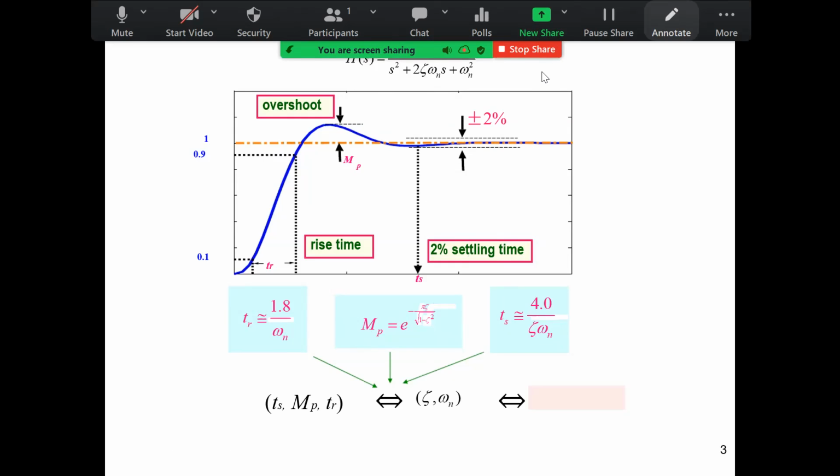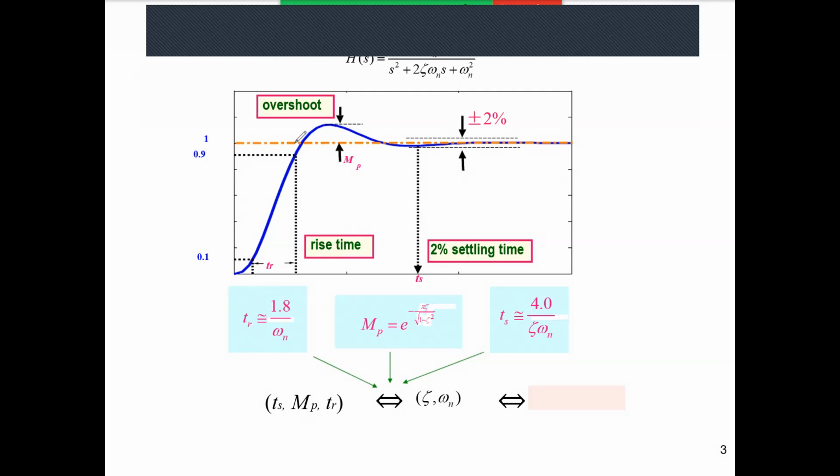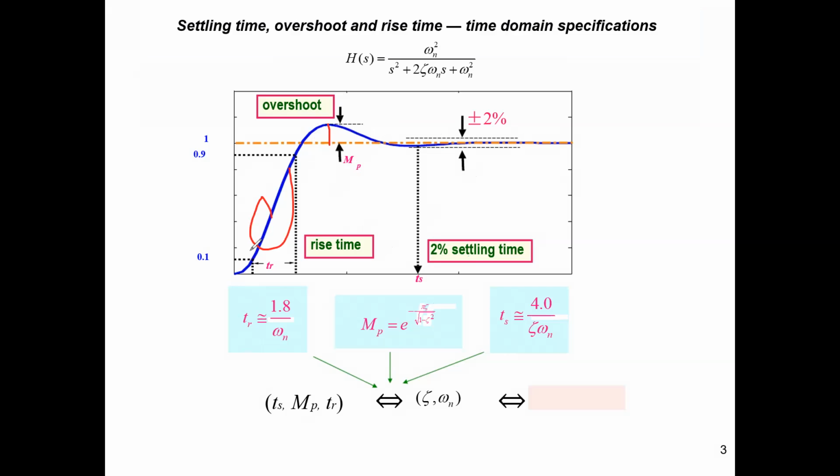simple, but some students have some difficulty. Probably I already showed you last time. For the overshoot, you have to look at the maximum value in this direction. The maximum value around here. Let's say now the steady state is 1. Of course, the maximum value should be over 1, bigger than 1, and the peak value, you take that value, you compute. Whatever happens, this part is not relevant to compute the overshoot.